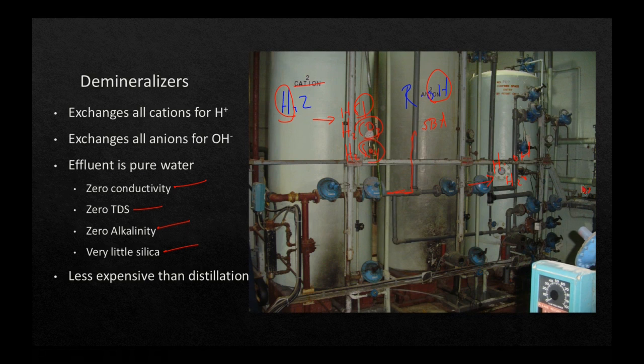And over here there's a little testing station where we would test two things. Number one, conductivity. Number two, there was actually a sample going to an online silica analyzer that would do a real-time silica analysis.